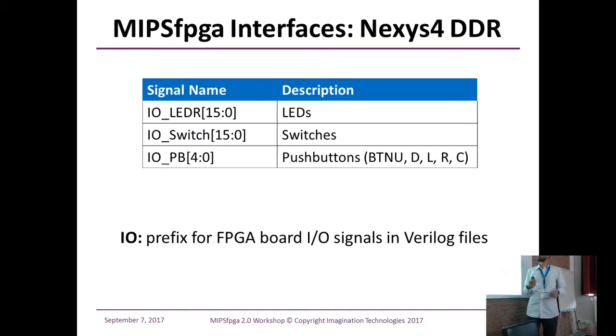The signals that are connected to the board's LEDs, it's prefixed with IO, IO underscore LEDR, the red one, IO underscore switch, 16 LEDs, 16 switches, IO underscore push button. There are 5 push buttons on the board, so these are wired out onto the board. Okay.